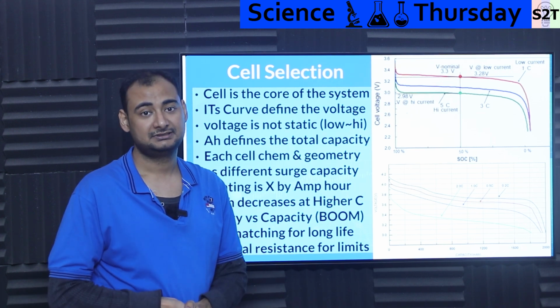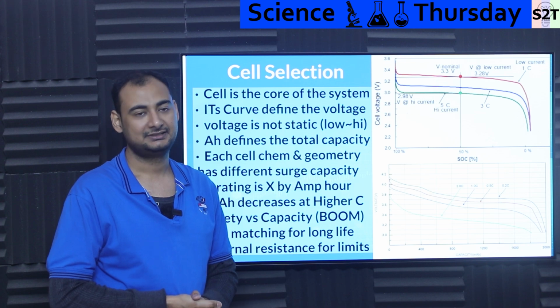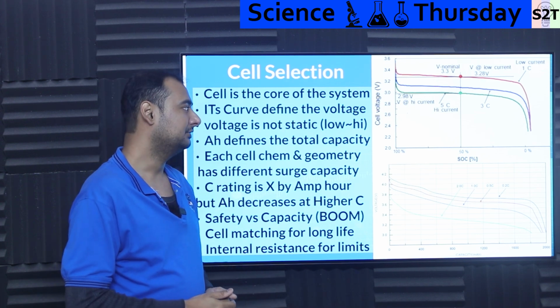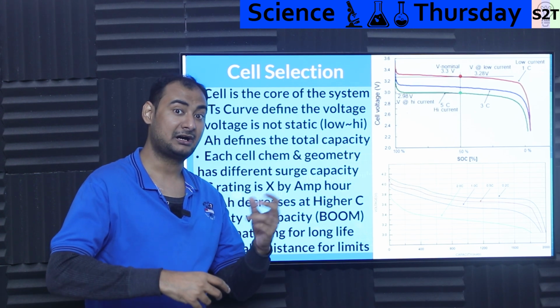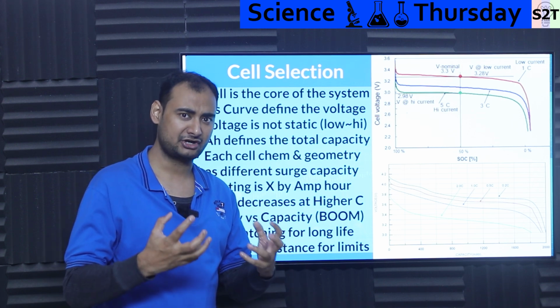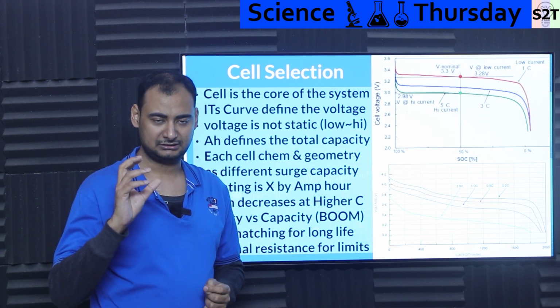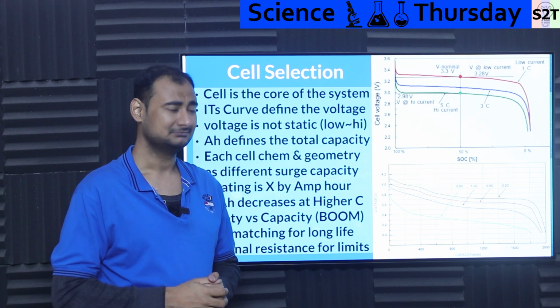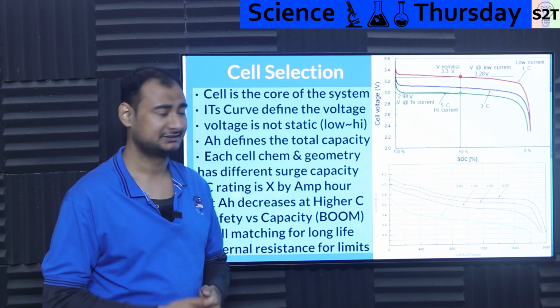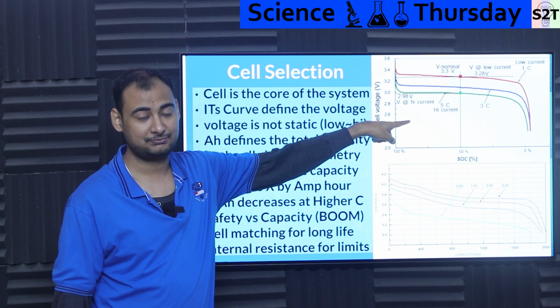You cannot just say, oh, it's a 3.6 volt system. Again, what C rating? What is your intended C rating? So let's say, for example, you say, hey, I want a small battery pack that can do power delivery charging, 100 watts of charging. Can your lithium ion chemistry support that? Absolutely. The problem is your capacity will shrink and your voltage will drop way too quickly.